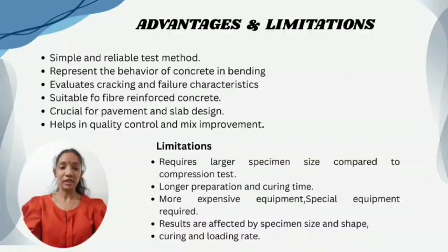Then limitations. Despite its advantages, the test also has some limitations. It requires larger beam specimens than the compressive strength test, making specimen preparation more time consuming. The test also requires specialized equipment which increases the testing costs.